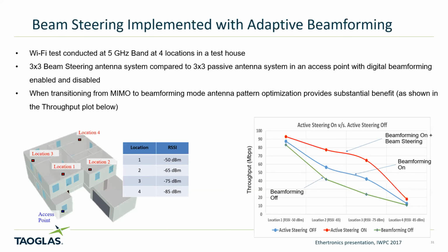One of the questions is, what do you think about stamped metal antennas? They can be quite robust and have better efficiency perhaps, especially for small form factors. They're very cost effective for high volume production. One of the limitations, as found in the smartphone years ago, is that it tends to be a 2.5D structure. You can stamp and bend it, but typically you don't have full 3D freedom for displaying a conductive element.